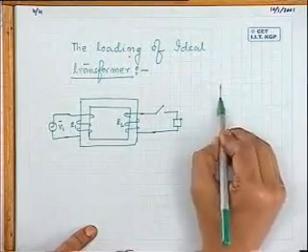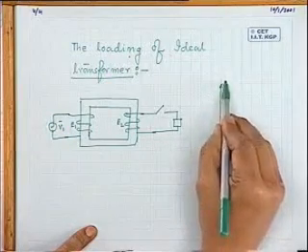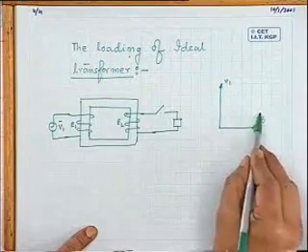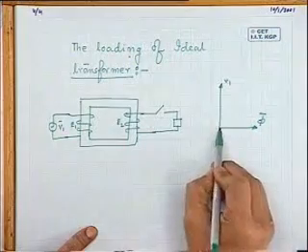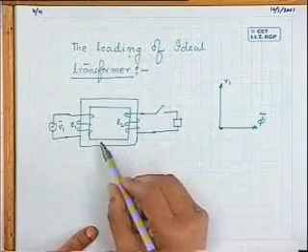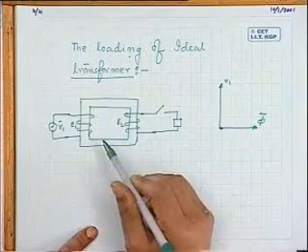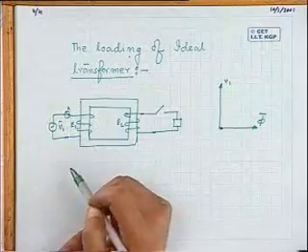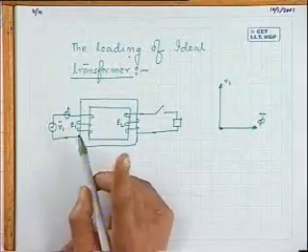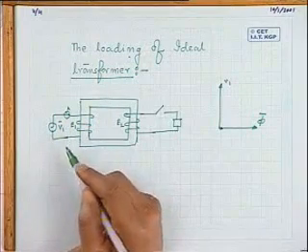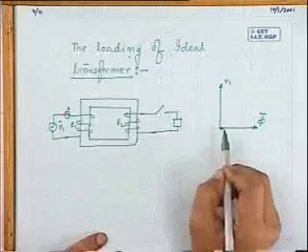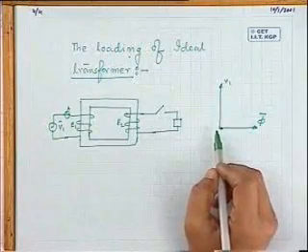Since it is an ideal transformer, prior to loading, this was the situation. This was the applied voltage. Yes, there was flux decided by supply frequency and the applied voltage. But the current drawn was very small, because I have assumed its permeability is very large. That is, if you connect an ammeter here, it will read no current, and it should not disturb anybody. That is what I want to tell. Because of our assumption, I have assumed very good magnetic material, which requires vanishingly small current.